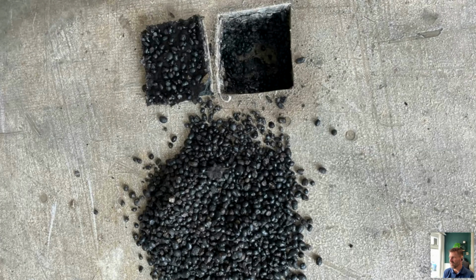Like I said, it is called insul screed, and it's also there to provide falls as well. That's just something that you might come across. I would probably always recommend to strip and remove that these days and put a tapered insulation system back down in its place.